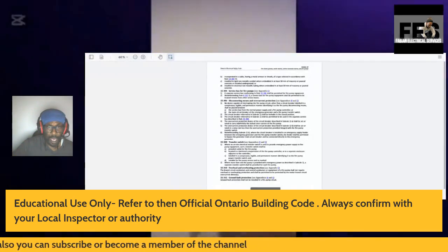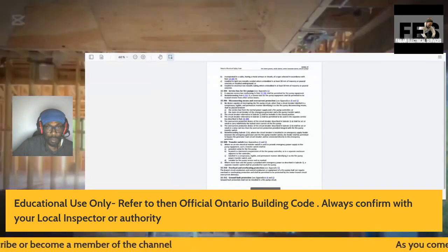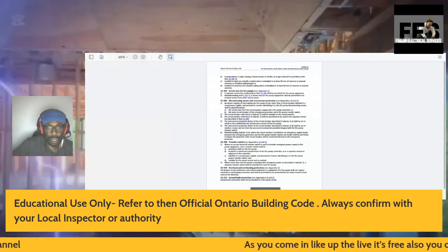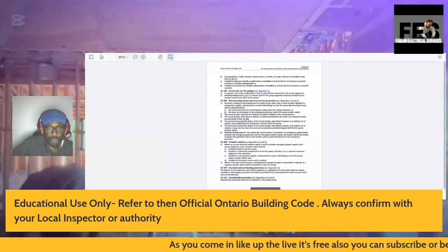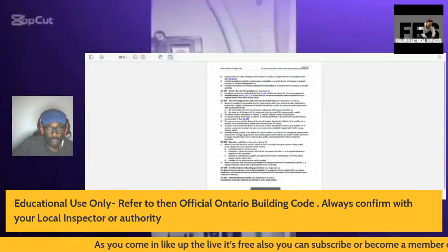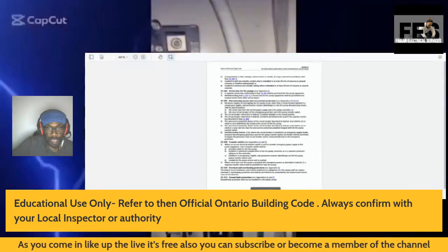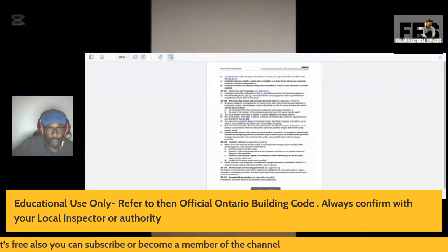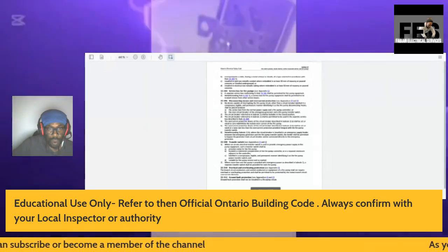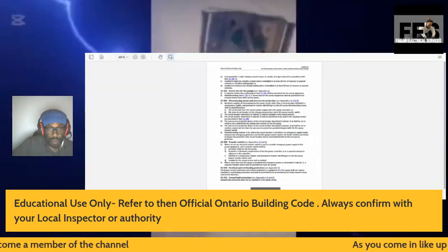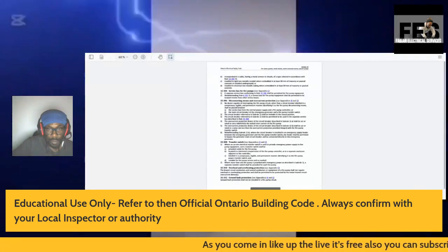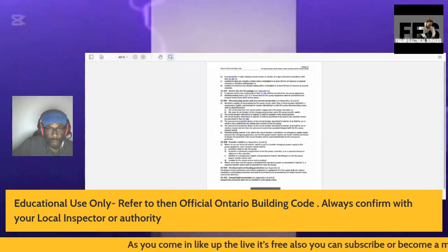Incorporated in a cable having a metal armor or sheath of a type selected in accordance with Rule 12-102. Installing rigid non-metallic conduit where embedded in at least 50 millimeters of masonry or poured concrete, or installed underground, or installed in electrical non-metallic tubing where embedded in at least 50 millimeters of masonry or poured concrete.